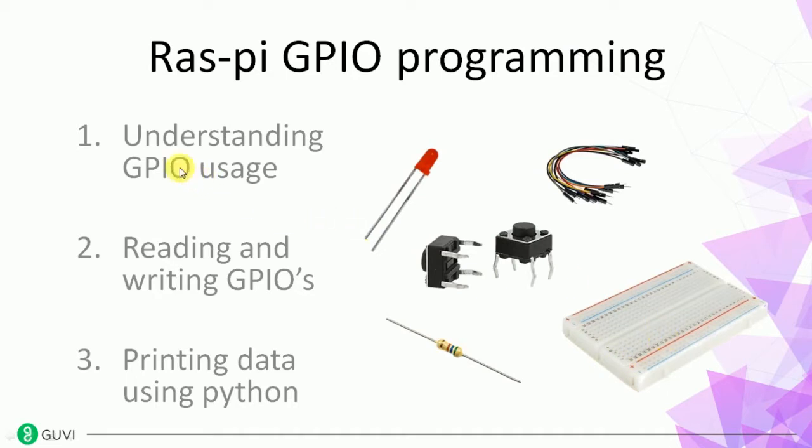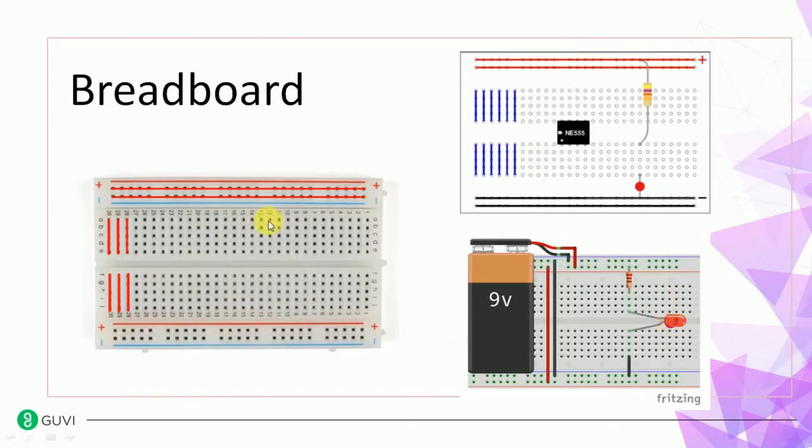We'll mainly understand GPIO usage, how to read and write values on GPIOs, and we'll print some data on our monitor. Okay, so this is the purpose. Let me explain a little about how to use a breadboard, for those who are not aware of it.